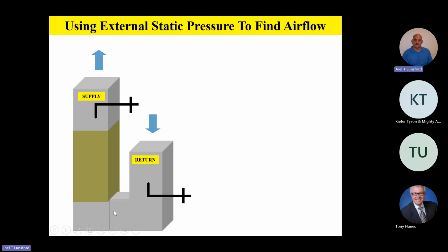And then if you want to put the filter back in and take another one just to see how much pressure drop you have across the filter, that's not bad practice. That's actually pretty good practice. But just remember, if your filter happens to be between where I'm taking my static pressure reading on the return, like right here where my cursor is, then make sure you understand you're going to need to take it on the other side of the filter as well.